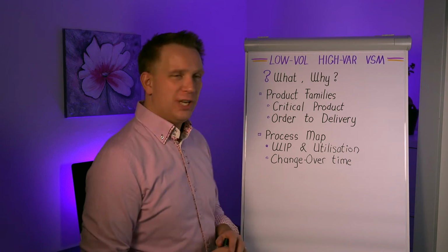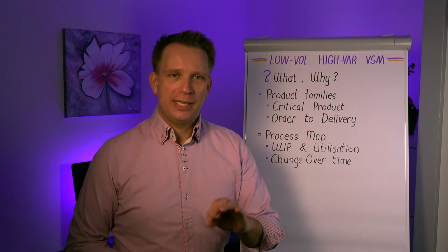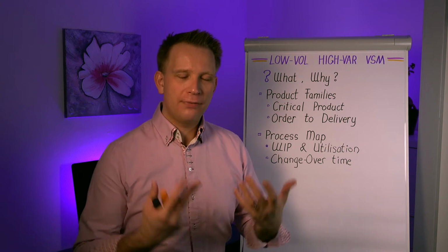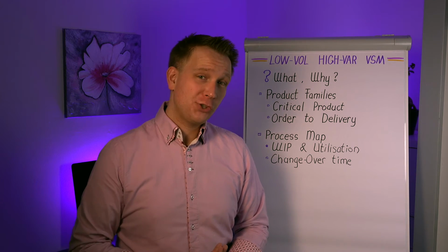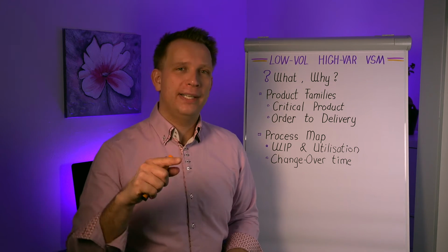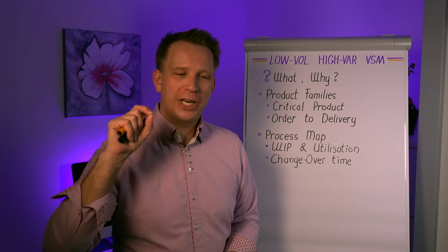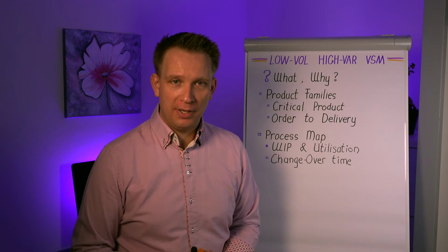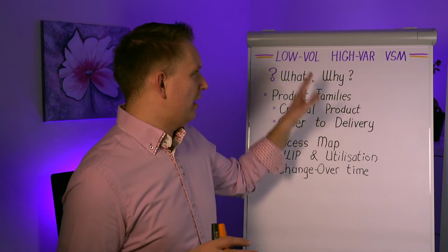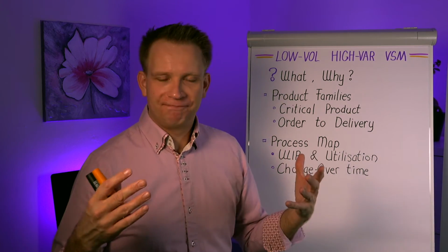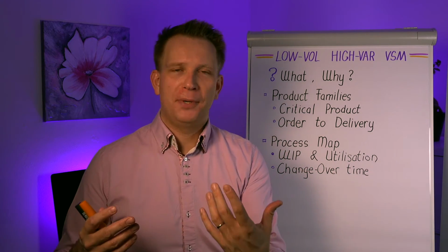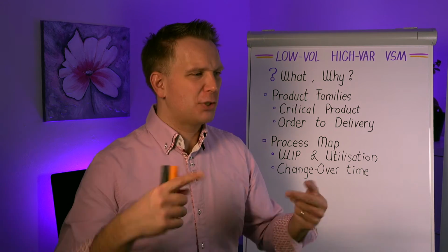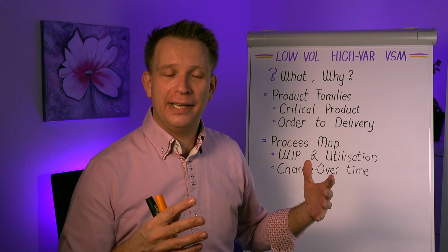So look at those changeover times. Any machine that has a high changeover time, a difficult and long changeover to do, and especially if you need to prep it well in advance, those are key areas for improvement. See, when you have that high variation and something didn't come out of a previous process, or an order of parts just shipped in too late, and at the last moment you have to switch to the next one in the line.